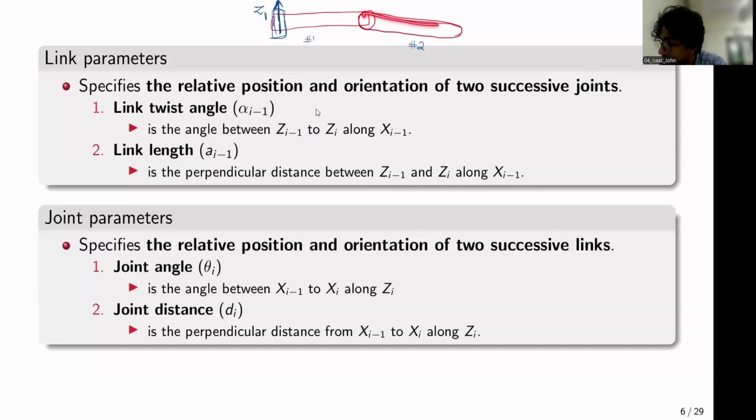And for the second link, something like this, the direction of the joint angle is out of plane, right? So if you consider this to be the rotary joint, the axis of the rotary joint is basically coming out of plane. So I label this as Z2. So the major distinctive feature of this DH parameters is that the first step while assigning frames is that the z-axis should always be along the joint.